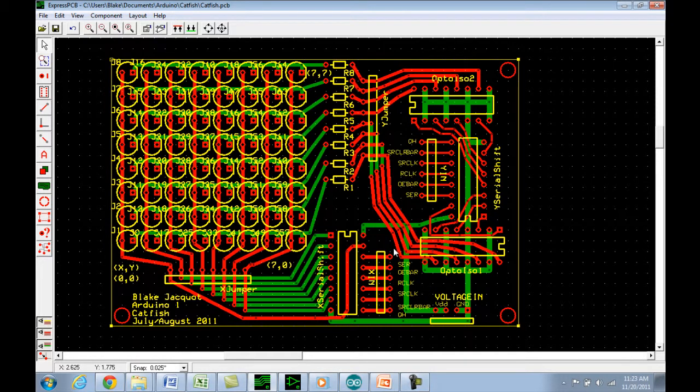It's pretty simple. I didn't include any bypass capacitors or really any consideration at all for high frequency because I'm only operating up to a megahertz tops, and I didn't think it was worth the effort to consider those things.